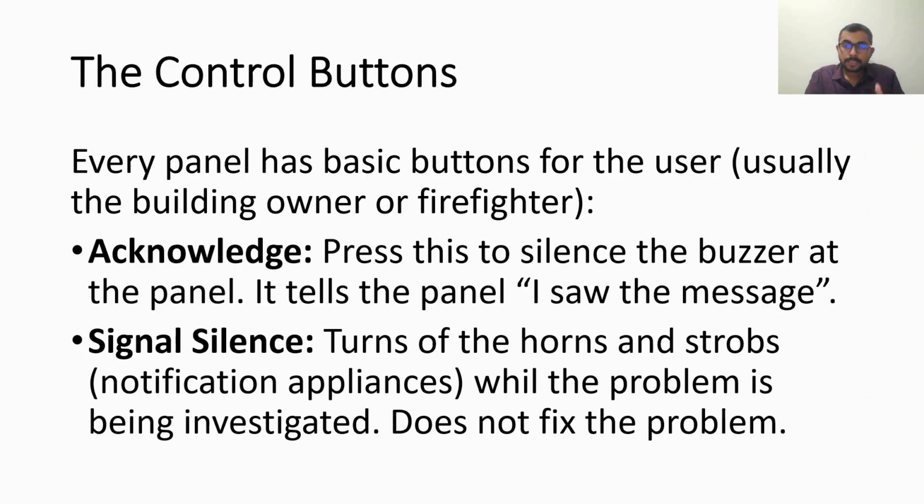Now let us discuss the control buttons which are available for the user on the panel. These control buttons are normally operated by either the building owner or the firefighter. The first one is acknowledge. The panel has an internal sounder. If the internal sounder keeps on buzzing or makes a beep sound, then the user can press the acknowledge button to silence the panel.